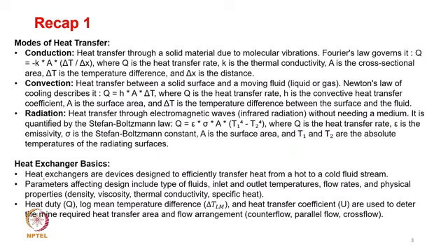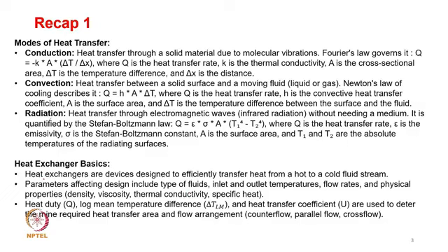Then we did heat exchangers. Heat exchangers are process devices designed to efficiently transfer heat from a hot fluid to a cold fluid. The parameters affecting the design include the inlet and outlet temperatures, the flow rates of the hot and cold fluids, and physical properties such as density, viscosity, conductivity, and specific heat. They are all directly involved in the heat transfer calculation, and that is why they are important.